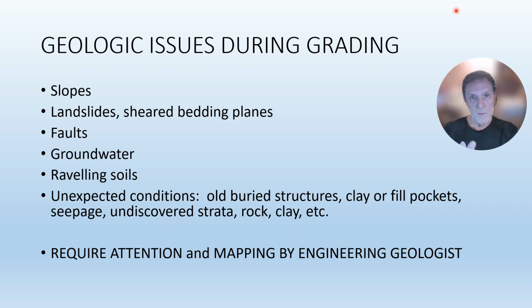You have faults. You may have inactive faults, which are not treated as equally as active faults. For active faults, you may have construction setbacks where you have to set buildings away from the trace of the fault, 25 or 50 feet.